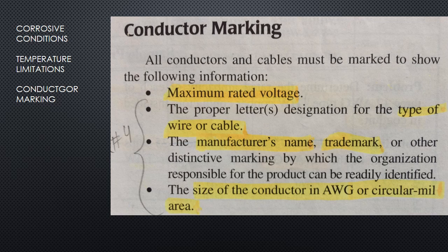The operating temperature of a conductor is determined by the heat produced by the resistance to current flow and the rate at which this heat is dissipated to the surroundings. Greater current flow and greater resistance in the conductor produce more heat.